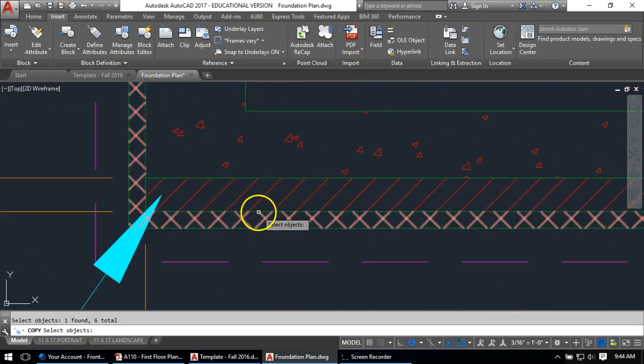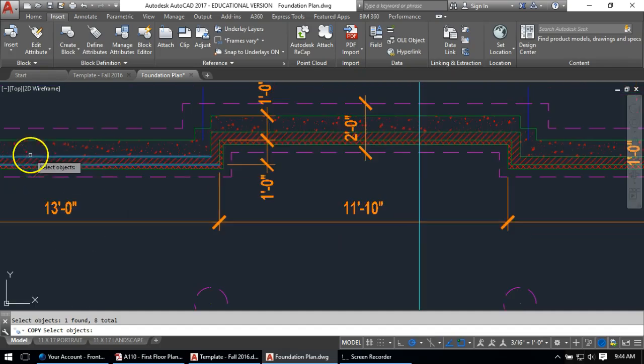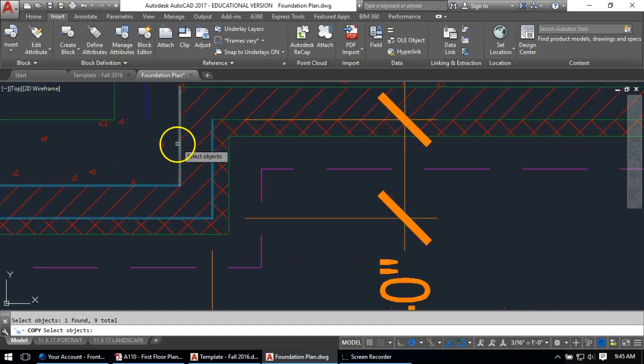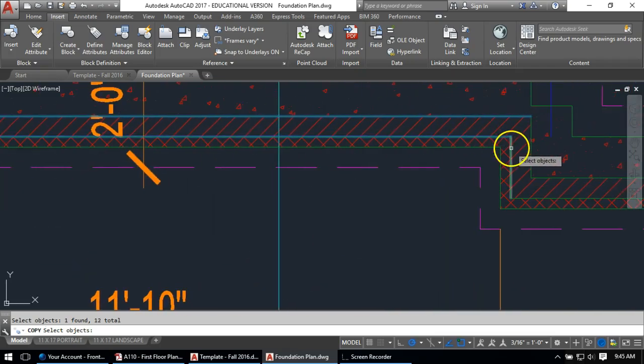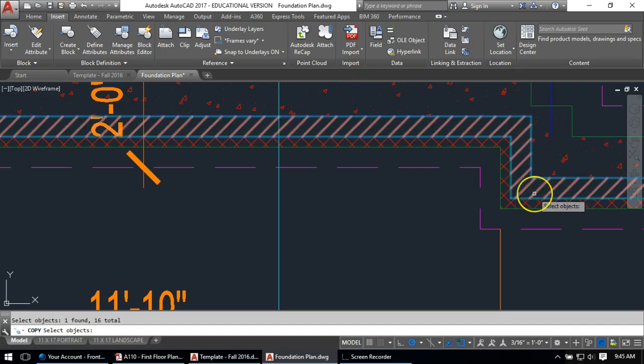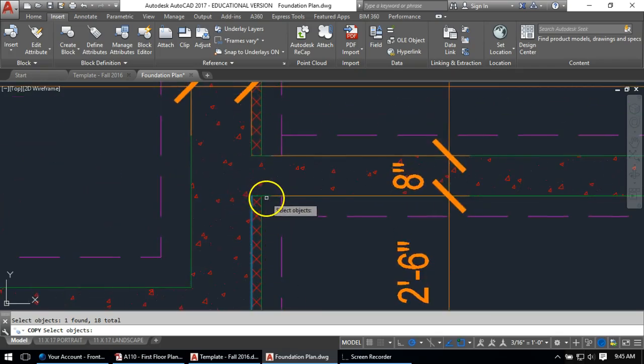And I might come and fillet this in, but we're actually going to have in the first floor both the brick coming up, as well as the concrete that our studs will sit on. So I can actually grab both of those lines at this point in time. Come through. In fact, I can probably grab that hatch, although I might have to edit the hatch later on because there's probably going to be doors and or windows in this file. Haven't looked closely at that yet.